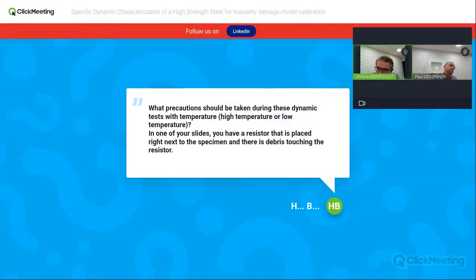So you see some inductive heating coils, and you see a picture on the right of the target just heated. You see we launch some metallic sphere, and they pass through the coil. And after, when we get the right temperature, we have various thermocouples to see if the temperature is homogeneous. And so we make the validation test.